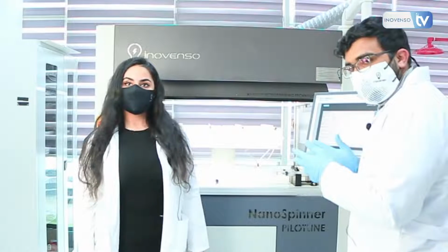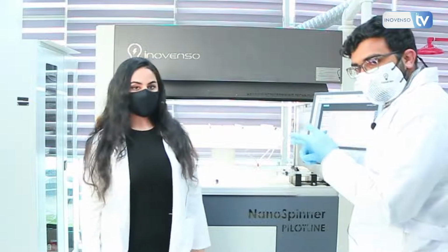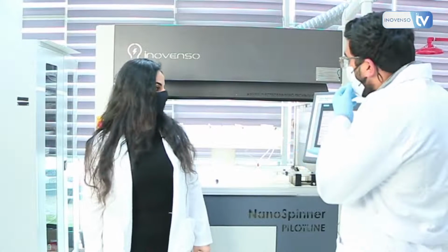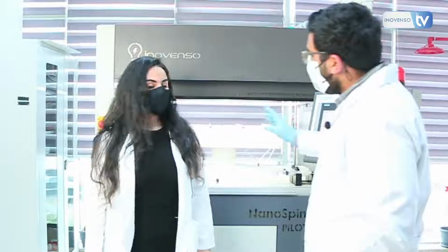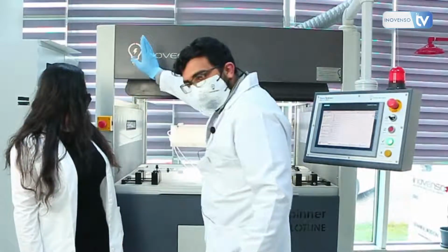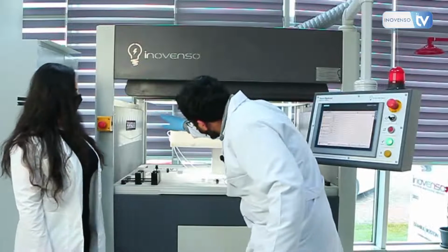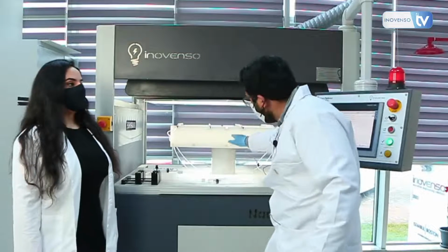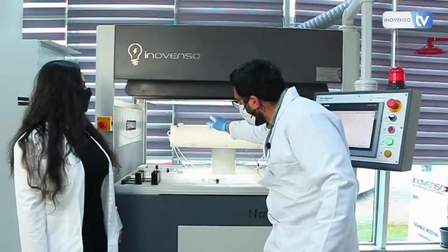It controls, this is where you will be operating the system. You will put in your parameters like the high voltage, the spinning distance, and the flow rate, of course, of the solution. So what you see on top of here is a roll-to-roll collector system. You load it from there, and the substrates move and roll simultaneously while you are spinning from the hybrid nozzles from here.